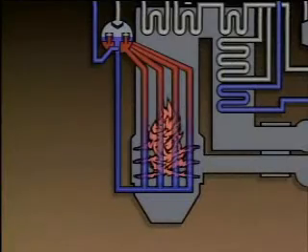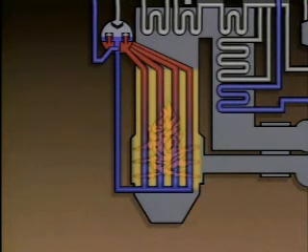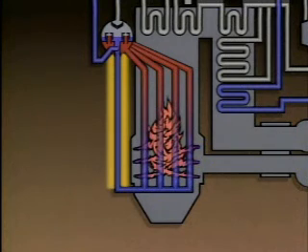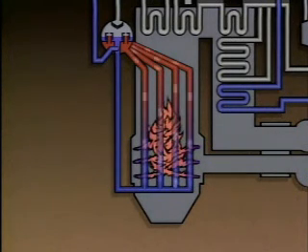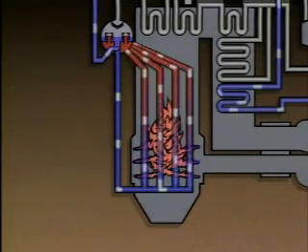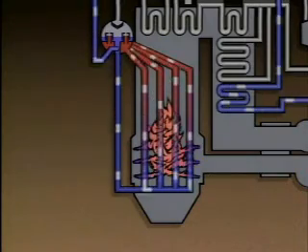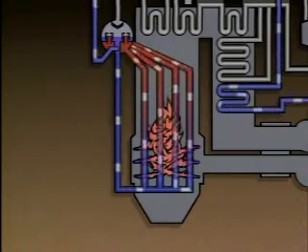The key to understanding natural circulation is the fact that cold water is heavier or denser than hot water or steam. In a boiler, the mixture of water and steam in the water walls is hotter than the water flowing from the drum through the downcomers. This is because the water walls are heated by the burning fuel in the boiler furnace. As the mixture of water and steam rises, cooler water from the downcomers flows into the lower headers and then into the water walls. The cooler water is also heated and rises, creating a self-sustaining flow through the water side of the boiler.